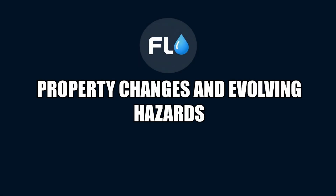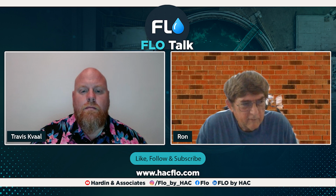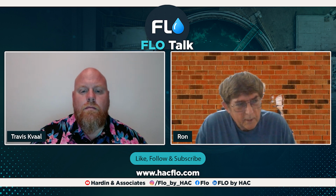Have you seen situations where property has changed and maybe the level of protection was proper at one point, but it's no longer proper? Yeah, I've seen things like where they added a swimming pool, and then they need to put cross connection protection on that. And I've also seen where they tried to fill the swimming pool off of the irrigation, which is another one you want to watch out for. I don't know if contractors just don't know, or they're trying to slip it in. You never know, but we see those kinds of things all the time.